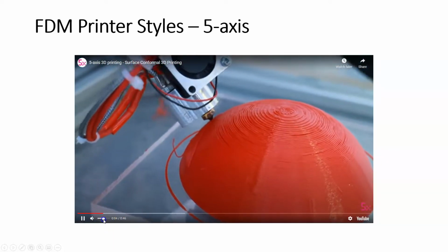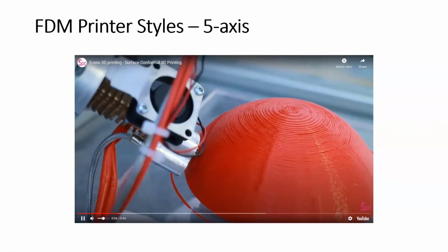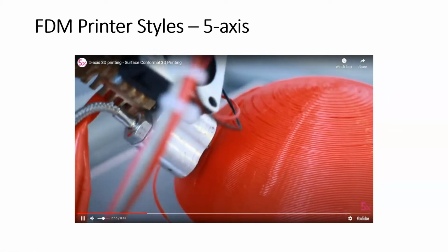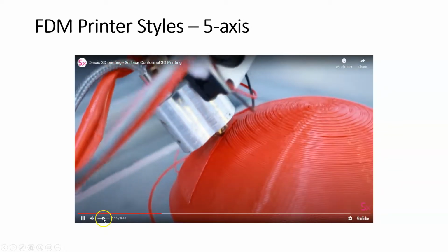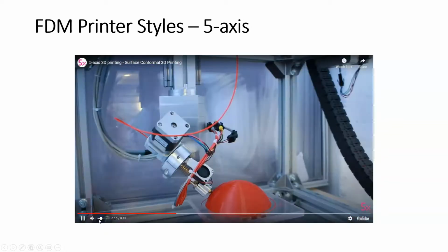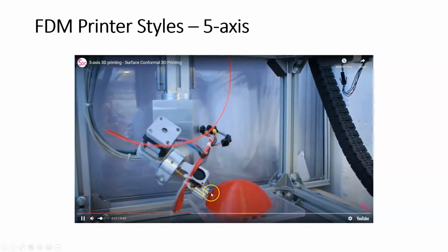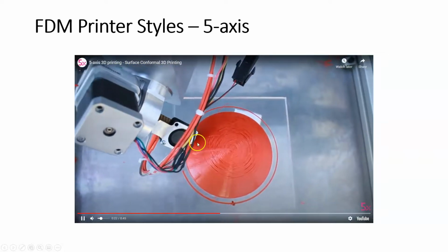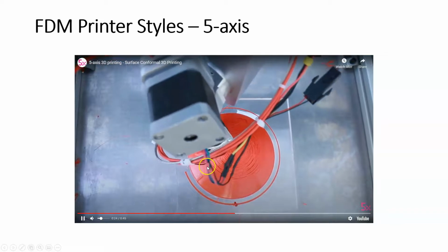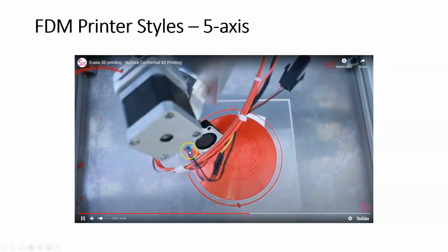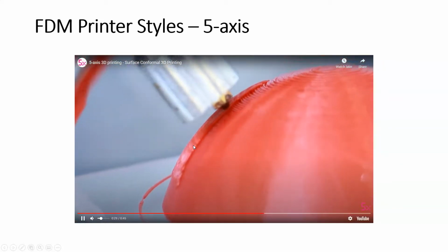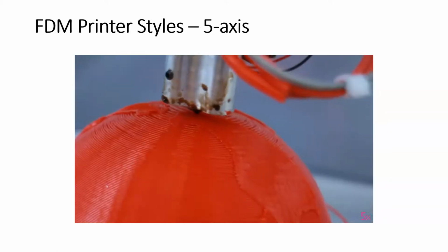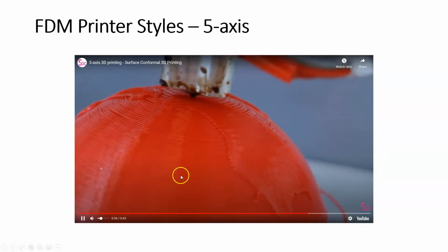Now I'll leave that on. That sound is the servos speeding up and slowing down, controlling that head. And the advantages here is that we can print over curved shapes. So notice that in a traditional material extrusion 3D printer, we're constrained to print on a flat build platform. So here we can more control the contour of the 3D print. All right.